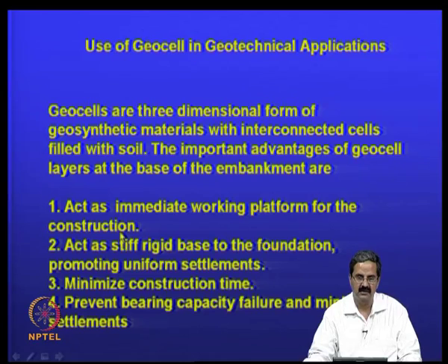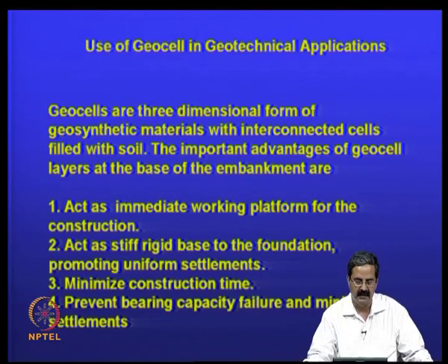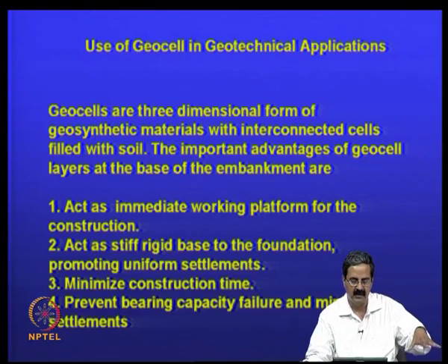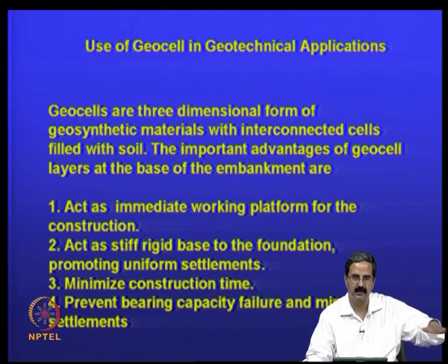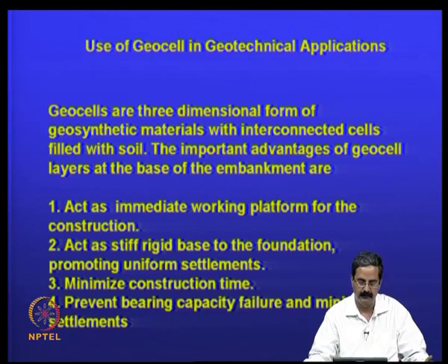for the construction. Say, for example, if you want to have a working platform and the soil is very soft, one can spread this geocell material and then start filling up soils. Actually, you can put a geotextile at the bottom, put a geocell, fill up all of those things, put a roller, and then use it as a platform.